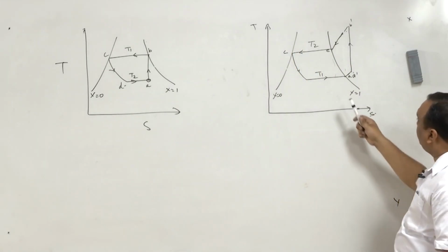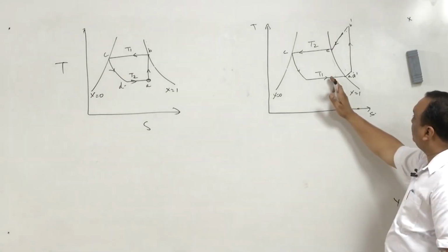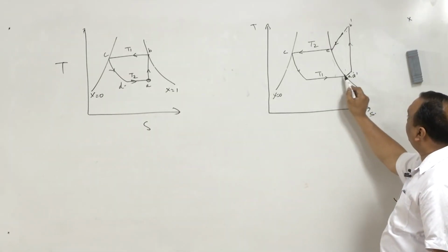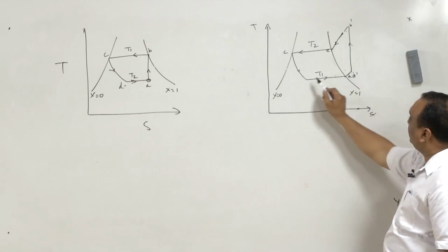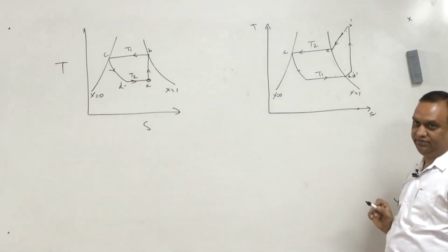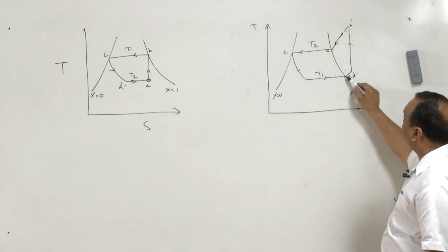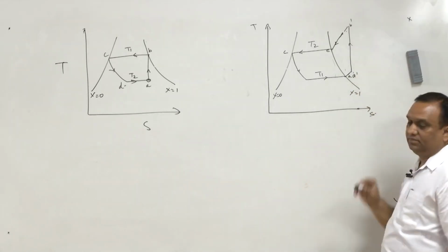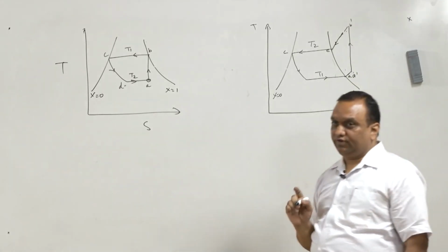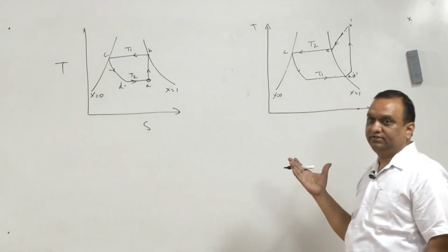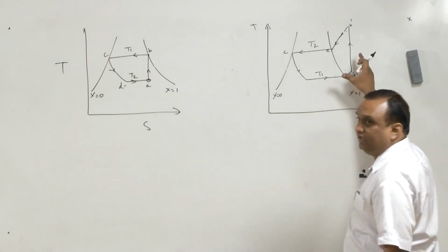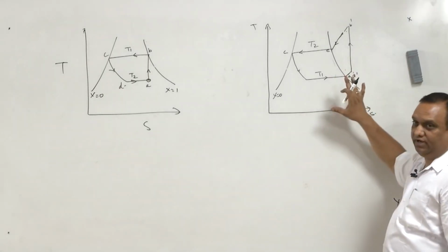And at the same time you can see when we are shifting towards the right, it means when the vapor which is entering the compressor is saturated, the refrigeration effect is also increased. The vapor is further superheated, which also increases the refrigerating effect. At the same time the compression work is also increased. So, there are two possibilities: either their ratio shall increase or it will decrease.